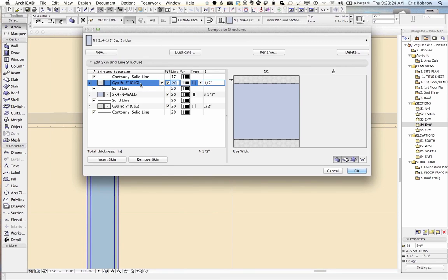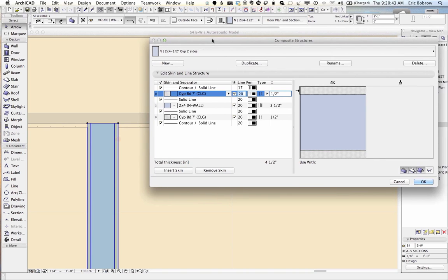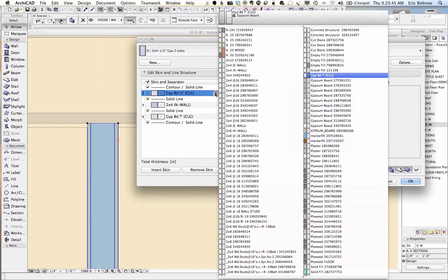So that's our problem: you're using a material for the wall that was designated as a ceiling gypboard that had a higher priority. And that's why, in this case, the wall one is going all the way up and the ceiling one is stopping short. So what we'd want to do is change this. Now, we've got a huge mess here in terms of the building materials.